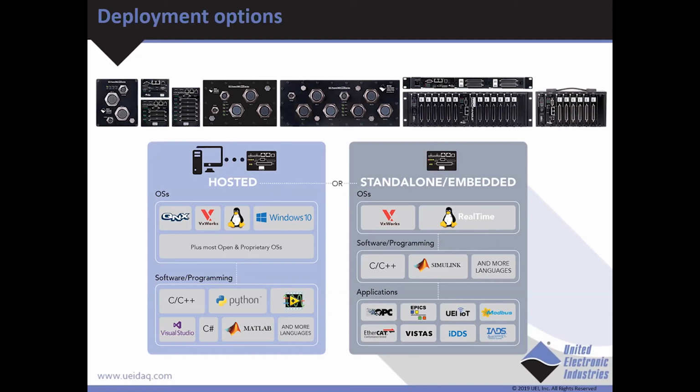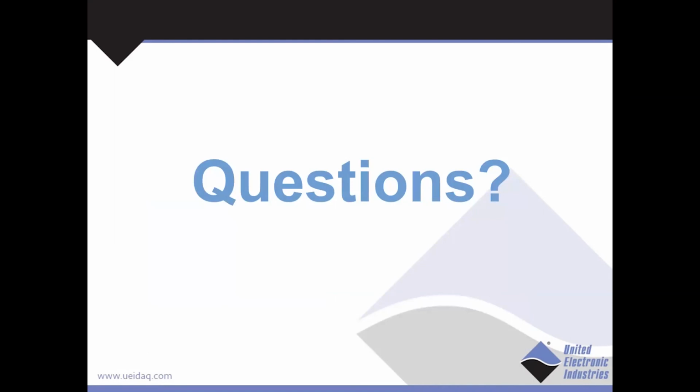I will have a quick look to see if we have any further questions that have come in. The first question is, do you support hardware for fault insertion in HIL? Yeah, we have 3-to-1 multiplexer boards, which you could use to switch between fault signals and simulated signals. This way, you can switch between your simulated signal, or you can insert faults by switching to the other input.